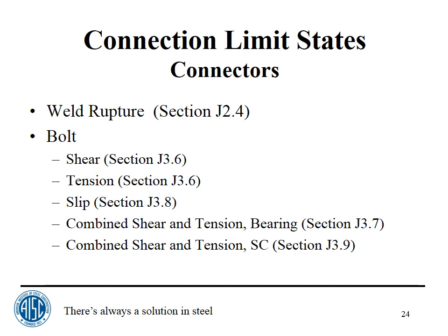I think the feeling is that the weld limit state itself is a rupture limit state, and the base metal is right next to the weld, so therefore it doesn't make any sense to have a rupture limit state on the weld and a yield limit state on the plate right next to it. That's the only explanation I can give. I really wasn't involved in when this was done, but I think it's a step in the right direction.